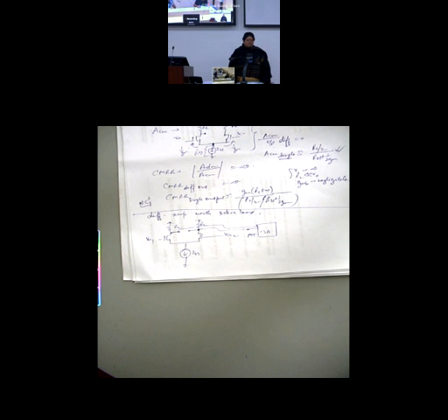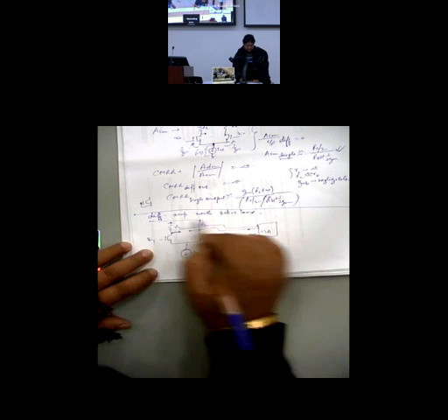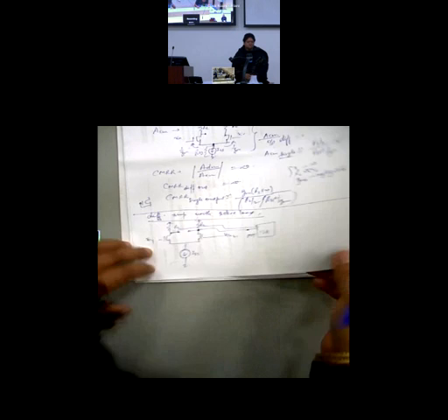Low frequency gain is also called the DC gain. It's not related to DC voltage, remember that. Low frequency gain is also called AC gain at low frequency, which means I call it a DC gain. So what to do? Can I get the flexibility in cascading, and at the same time avoid a loss of gain? Here is what we now call a differential pair with active load.